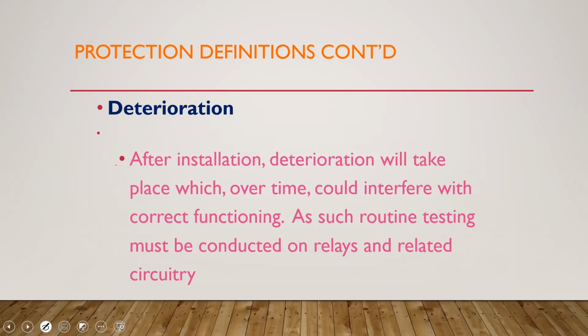So you may have low oil in the transformer, which means that some of the windings may begin to be exposed. It doesn't require immediate removal or discarding of the transformer. It just may mean that you have a leak somewhere and you need to correct the leak and add back oil to the system. So you have to maintain a system.